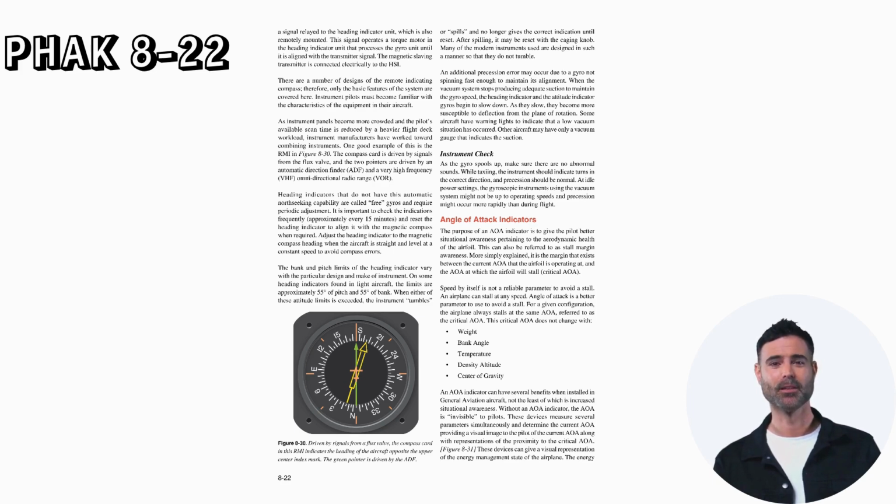The magnetic slaving transmitter is connected electrically to the HSI. There are a number of designs of the remote indicating compass. Therefore, only the basic features of the system are covered here. Instrument pilots must become familiar with the characteristics of the equipment in their aircraft.